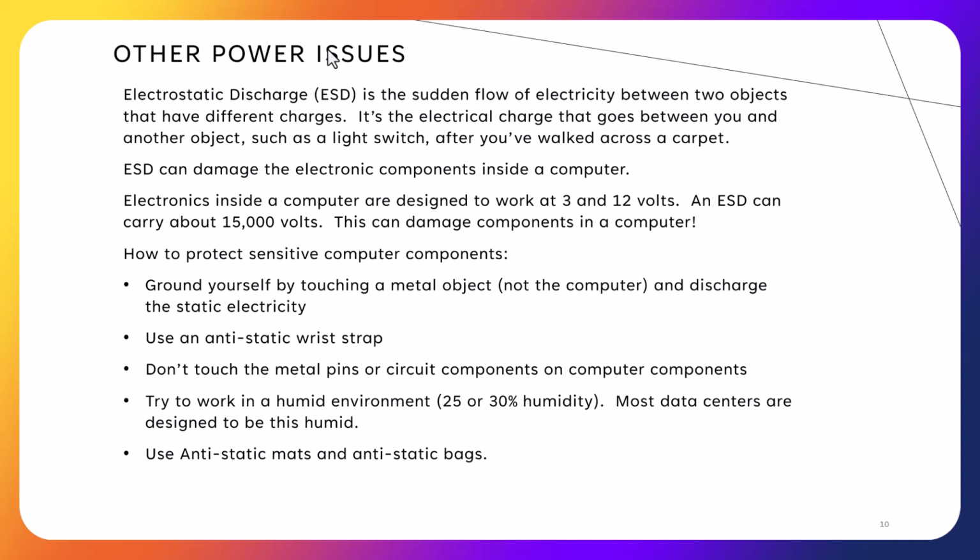Try to work in a humid environment, 25 to 30% humidity. If you're in a data center, data centers are usually operating in the 20 or 25% humidity range. And then you can use anti-static mats, and if you ship devices or carry devices from one location to another, use anti-static bags.